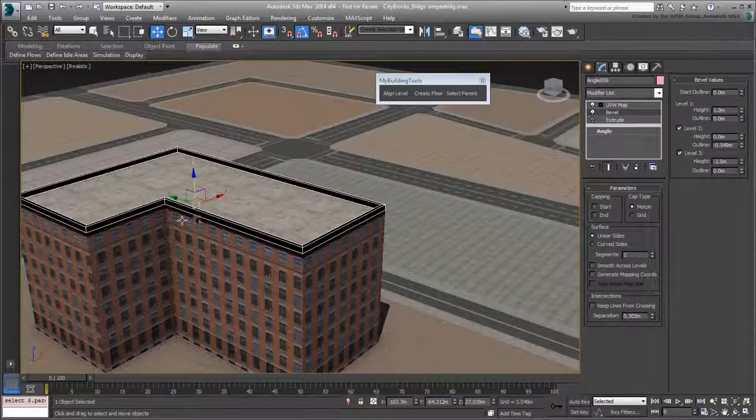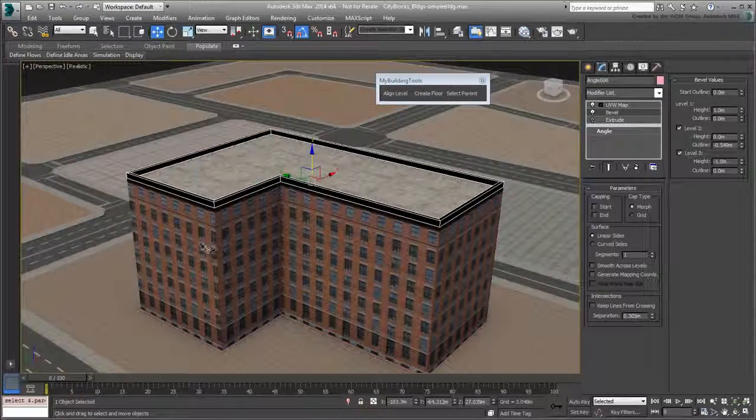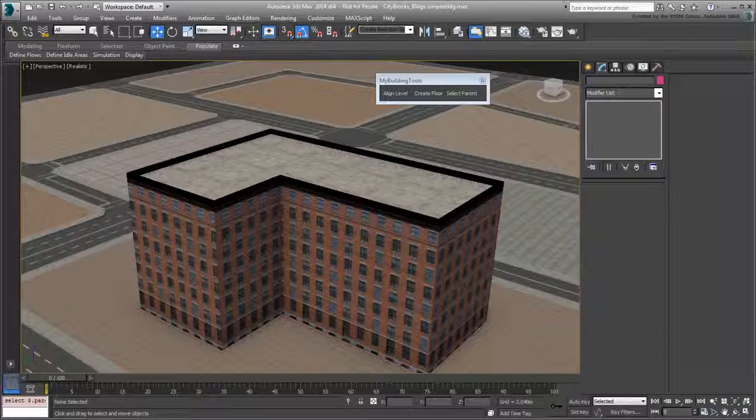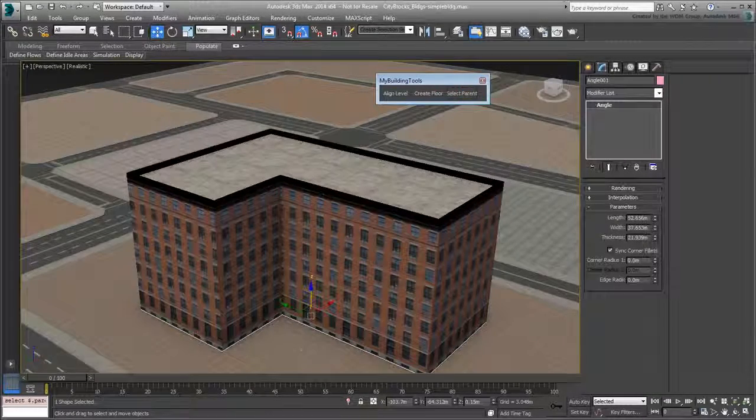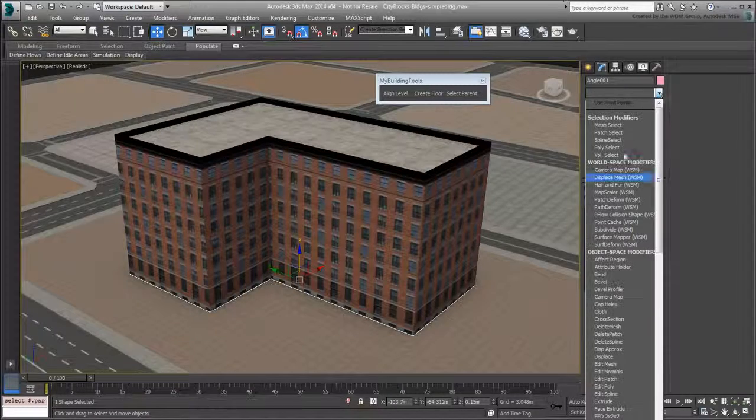Finally, let's take a look back at the importance of the original 2D shape. You've already made use of it to help with some of the scripting lines. Most importantly, because of the method you adopted by making use of reference duplicates, all extruded floors are still dependent on the original spline. This means you can select it and edit it, and all floors will respond to that change. Try it out. Select the original spline and add an Edit Spline modifier to it.